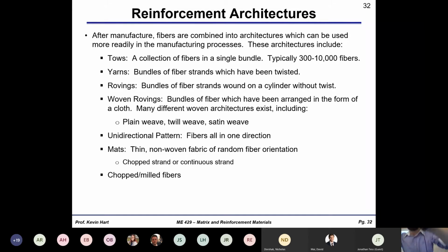I'll pass this around. And maybe if you want to pull some individual strands out, you can take a look. And you can just throw that in the trash when you're done. I've got plenty. But that is an individual carbon fiber tow, and that individual tow contains about, I think that's a 6K, meaning it's got 6,000 fibers in that one particular tow, right?